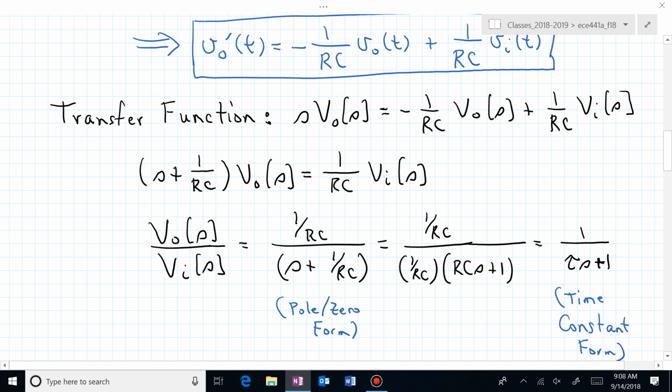And what's infinity? It's not very long, actually. It's 5 time constants. So anytime you get beyond 5 time constants, effectively you're at infinity. So when is infinity not infinity? In this class, when it's equal to 5 tau or 4 tau, depending on how we define our settling time. Is it clear then what I've done for this first order system?